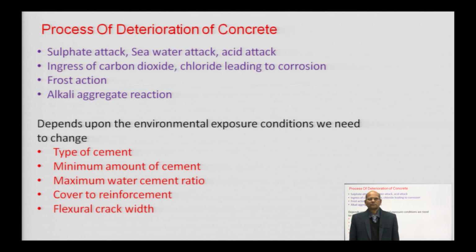Okay. So, depending upon the environmental exposure condition, we need to change the type of cement. Different types, depending on the requirement, we have to change. So, the minimum amount of cement is also fixed. For a particular environmental condition, either plain cement concrete or reinforced cement concrete, we have to give some minimum amount of cement.